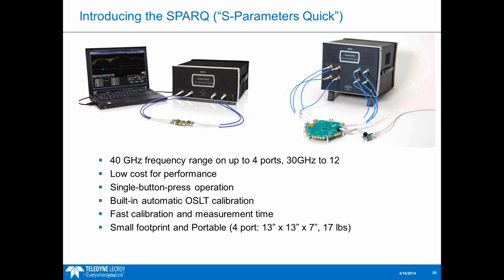But you can download the software for the Spark from our LeCroy website, and you can download that for free. It'll allow you to import S parameters into the Spark, and you can transform between time domain and frequency domain. You can show impedance, step response, or magnitude and phase of S parameters. Usually it's easier to find some software like the Spark software out there that'll do a lot of those transformations for you. But all the information is there in either domain. It's just a matter of converting back and forth to learn different things about the interconnect.